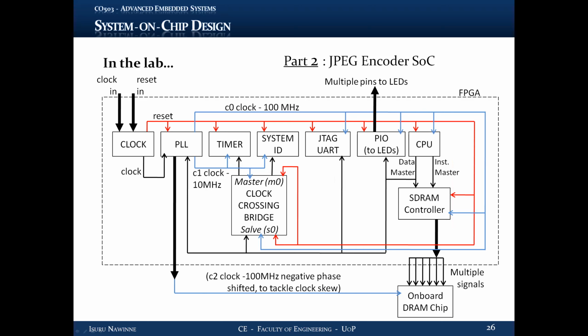So the idea is to have the delayed clock edge for the off-chip device and the regular clock edge for the on-chip device synchronized to the exact same time, so the communication can happen between them.